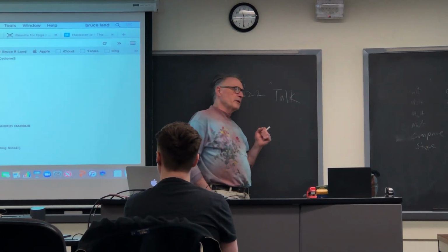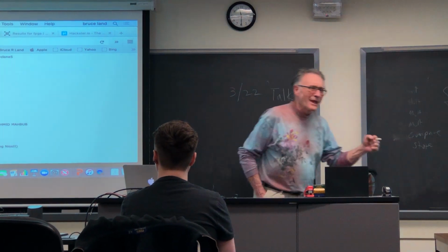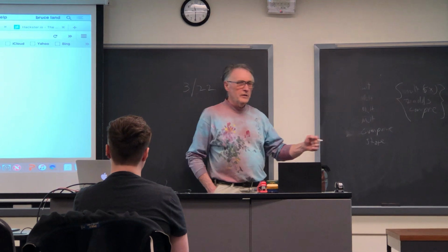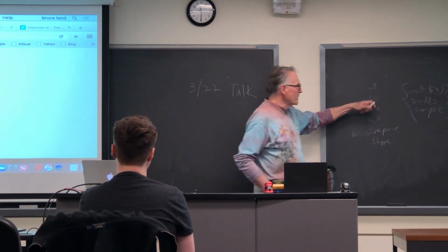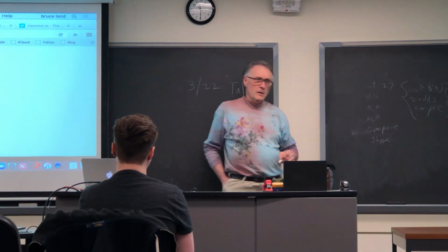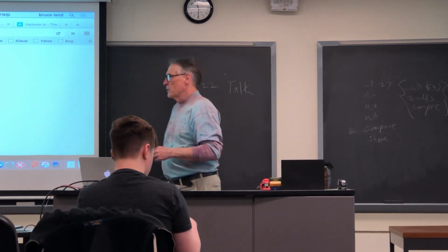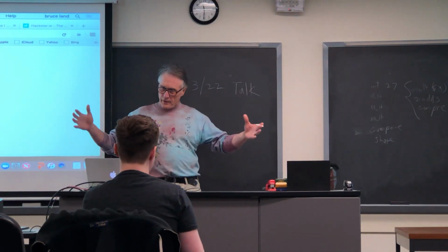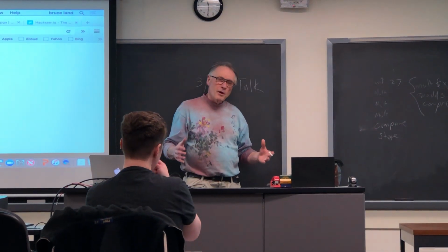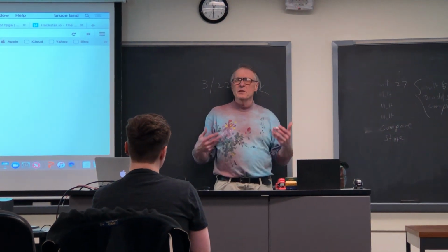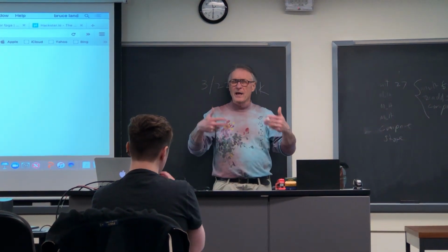I don't think you're going to need to turn on pipelining in the multipliers. You certainly are not going to need to do that if you use 27-bit arithmetic, because that only takes one multiplier. If you use 36-bit multiplies for better zoomability, then it'll run slower because there's a sequential multiply add.